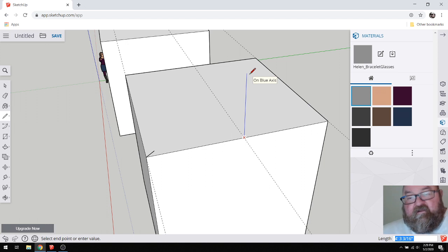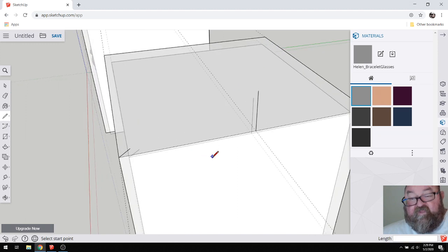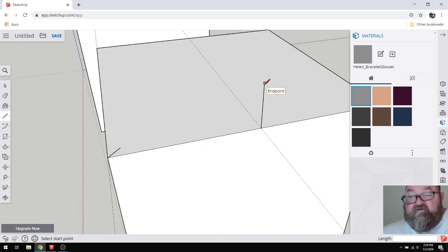And another thing to think about when we're talking about roof pitches is that you can go through this exercise in your mind. I know that 6 feet is my run, the span of my rafter. And so if I have a 4/12 pitch, that means I'm going to have 4 inches times 6, which is 24, right? So if I draw myself a 24-inch line, that would be the height of my roof, okay?